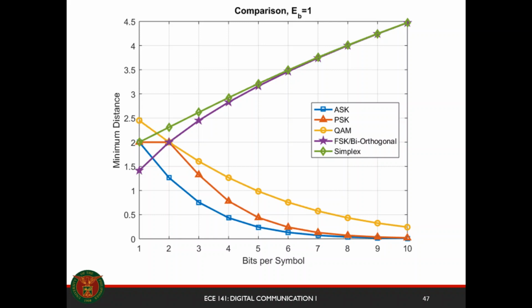So those are the challenges that you face when you're designing these systems. When you just design a symbol, there are so many considerations already. Consider the minimum distance between the symbols. You consider how much power they use. What are the trade-offs? Basically, it all depends on you. You need to be able to study the channel, create a constellation that is suitable for the channel. It depends on the application.